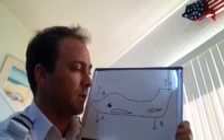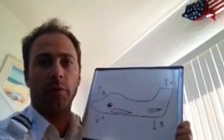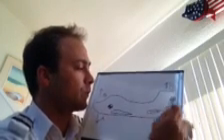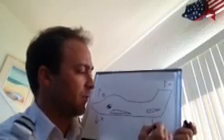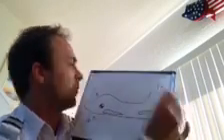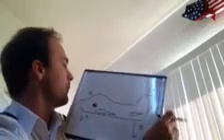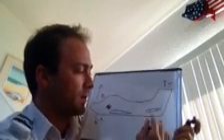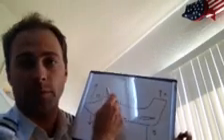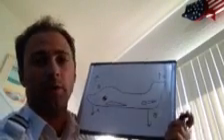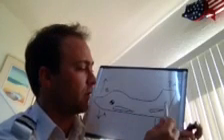But in this situation, like we said, we're imitating straight and level flight with a nose up attitude. And the opposite is true for a nose down attitude. We'll just pick nose up. So this means that our tail down force is too great, causing our nose to rise. So what do we do? Same scenario. Take the trim wheel, spin it forward through the linkages.